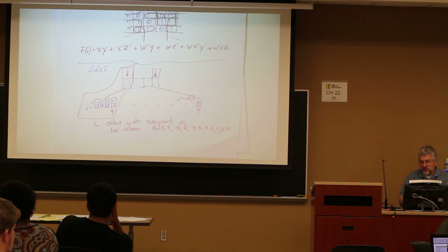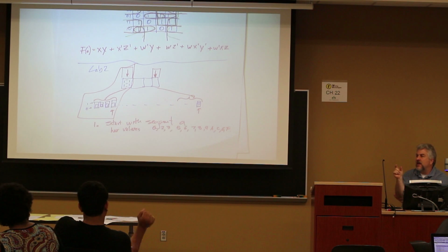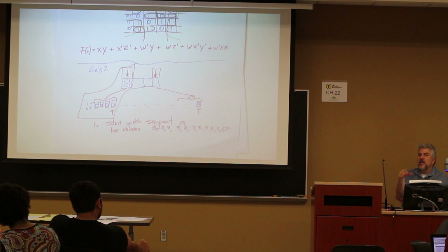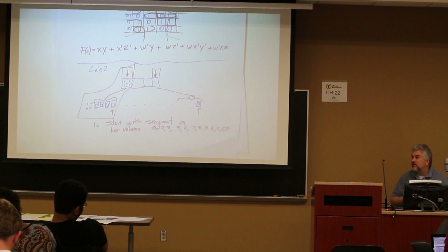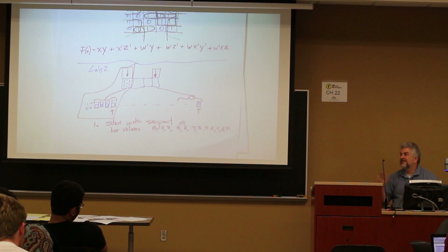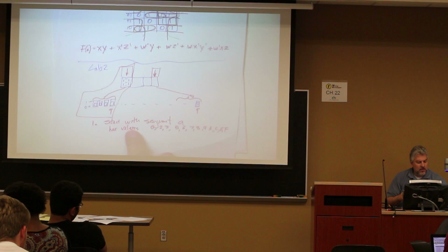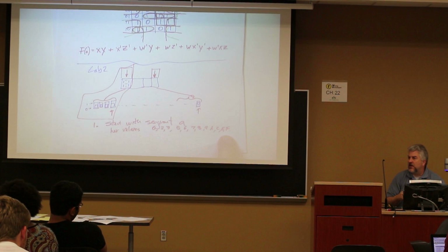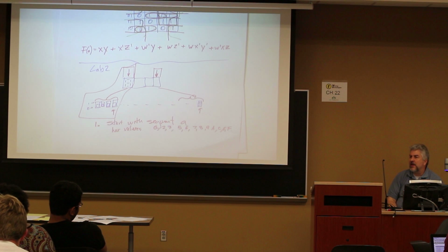So what you would do is you would start your exercise and you would only write in the equation for segment A. You would go through your build cycle that you've done already, right? And you know what? You could simulate this before you put it on a board. You would simulate it to make sure that, with the inputs that would be represented by these hexadecimal numbers, A actually is output in the right way.